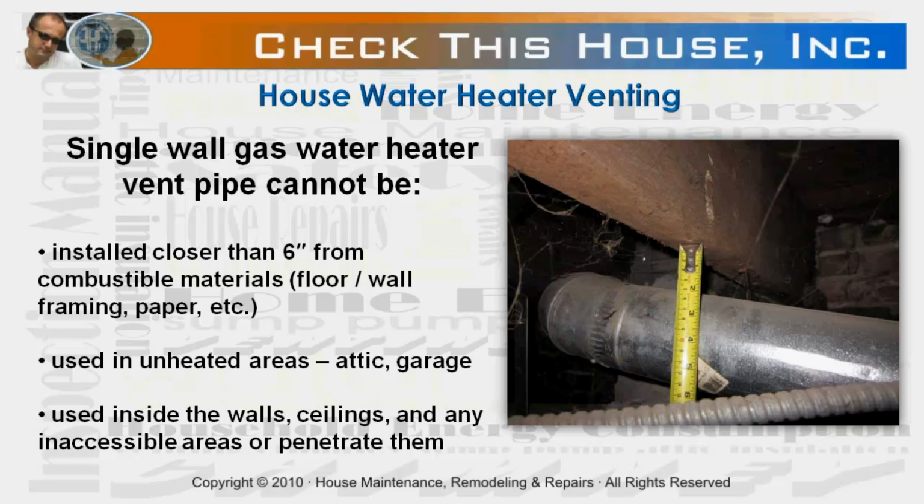And number 3, single wall gas water heater vent pipe cannot be used inside the walls, ceilings, and any inaccessible areas. Again, double wall type vent pipe B-vent must be installed in those cases.